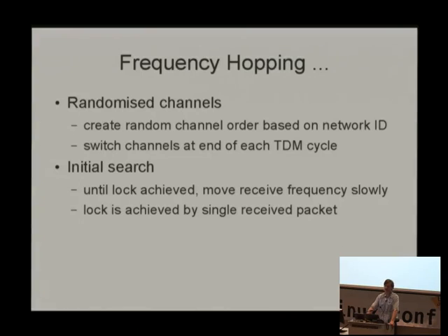And that packet has the trailer with the 13-bit number, which tells you how many microseconds he thinks is remaining in his window. So any one packet getting through allows the opposite radio to completely synchronize on the frequency hopping and the TDM, which means you then have all the information you need to be in sync from then on. And the clocks on these things, even with the different altitudes and different temperatures, where the crystals aren't quite great, it will stay in sync good enough for minutes. And that means you only have to get through sort of a packet every few minutes to keep in sync for this frequency hopping and TDM. So it really works very well.